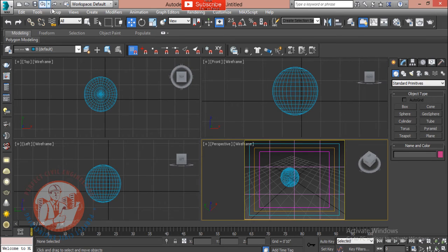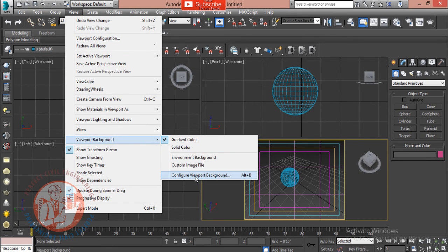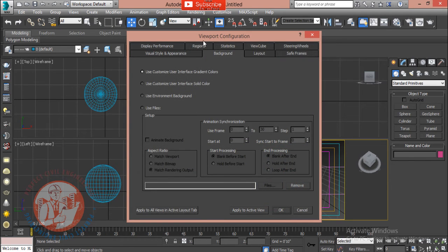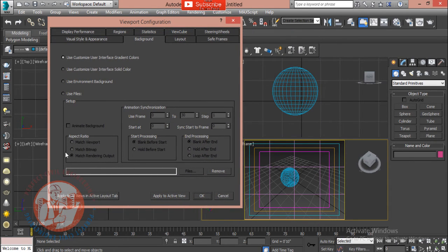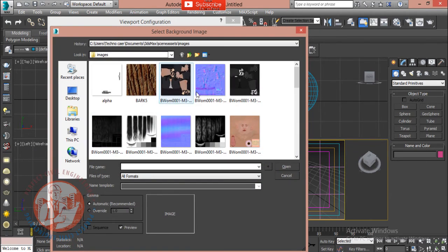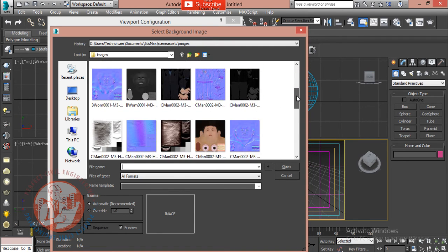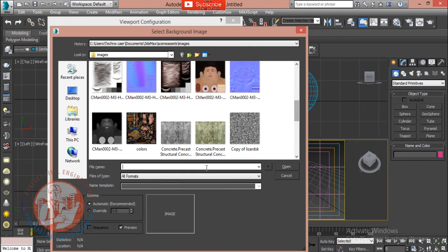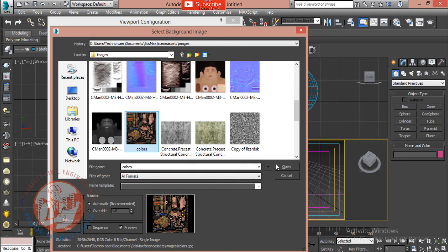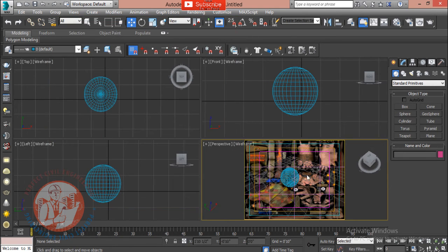Working with viewport backgrounds. Remember in grade school when you realized that you could immediately draw really well using tracing paper, where all you needed to do was follow the lines? Well, it's not quite tracing paper, but you can load background images into a viewport that can help as you create and position your objects. Loading viewport background images. The Views, Viewport Background menu command, Alt+B, opens a dialog box.